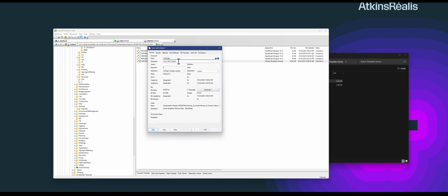So, because this is, like I said, a seed file, the first thing you need to do, my friend, always go to your coordinate system. I'm searching here up top, just COO, and make sure it's set to the right coordinate system before you start doing anything else. And for the people who are watching on YouTube, if you think my ORD looks different than yours, well, it's for a reason. If you don't know how, because I customized it, just go watch ORD 101. I already did that in it.